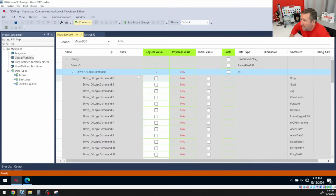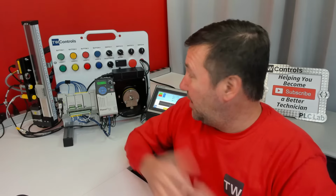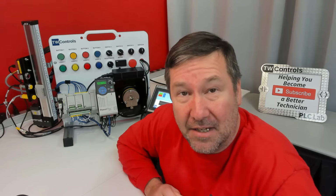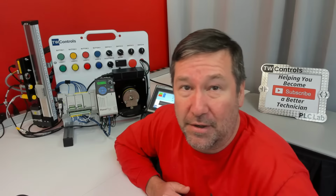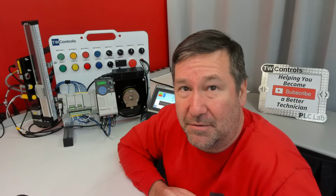So go ahead, and no, it won't work, so don't worry that it doesn't work. Just so we see, we're going to try to put a 1 into the start, and nothing happens. And the reason for that is I've factory defaulted this to make it where it runs locally. So P46 and P47 are the two parameters that you'll almost always need to change in the PowerFlex 525.